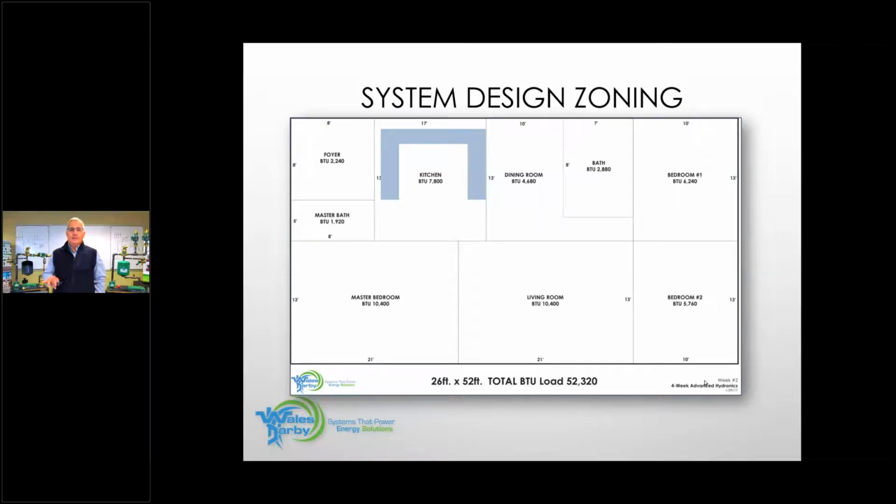So we've got some challenges in this floor plan here. And think of this as a ranch house. So I got no heat above, it's just a ranch, and I got my basement below. If I went with 2 zones, again, I see a problem here. Where would I put the stats? If I split the house in half this way, where am I putting the stat? Am I going to put it in the kitchen?